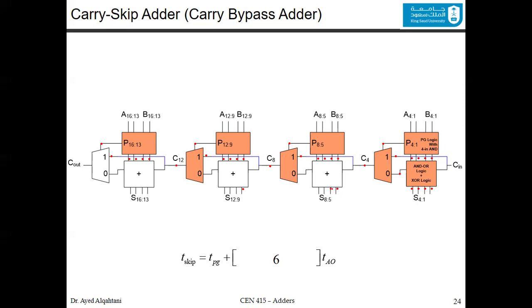And you already generated 2 bits here and 1 bit here. Now, for cycle number 7, you are working on the first bit here, and at the same time, you generated the third and the second here. And then continue. The more bits you have, the more bits you have in the other adders. So there's an interleaving operation between these adders. So at cycle number 9, you will generate the second bit of the last adder, which is this one. And you also finish this addition.